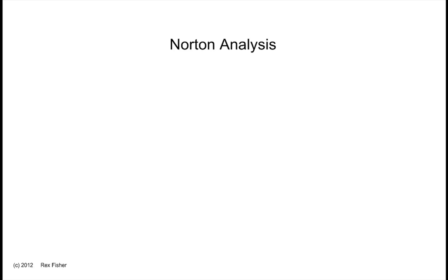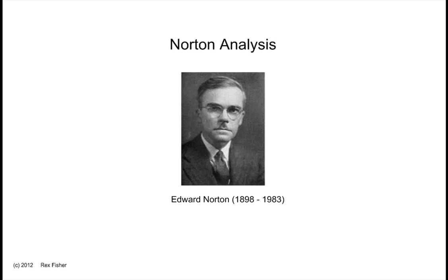This video is about analyzing electric circuits using Norton analysis. Here's a picture of Edward Norton. He and his co-workers at AT&T were some of the first engineers to apply Thevenin's theorem. But Norton worked with recording instrumentation that was mostly current-driven, so he proposed an equivalent circuit based on a current source and a parallel resistor.